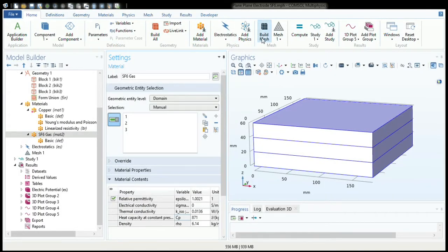Okay, for now let's look into the Comsol Multiphysics 5.5 software. To simulate an HVDC test in this software, we need to choose the proper file to start. So for this HVDC insulator test, I use 3D and choose DC for stationary.